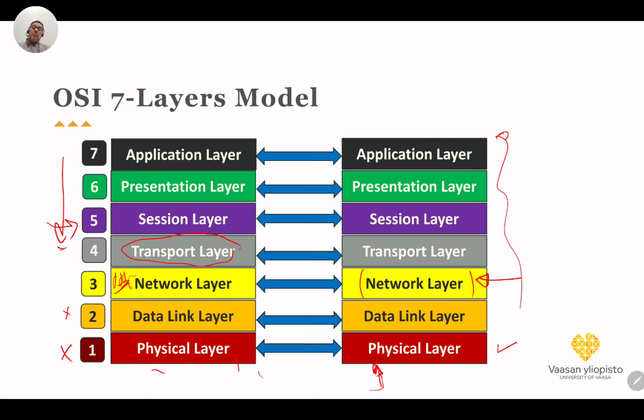In all modern communication systems we use this cross-layer optimization, so that when you design the communication system, the physical layer also depends on the application, on what you want to send. For example, if the transmitter wants to send a very high data rate, like video at 4K, and it requires certain specifications about the delay and the frame rate and so on, then the physical layer should be able to do that.